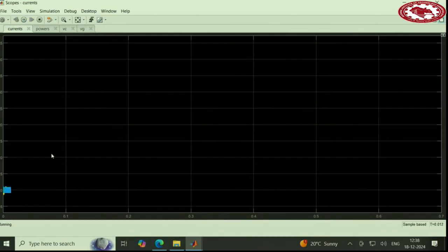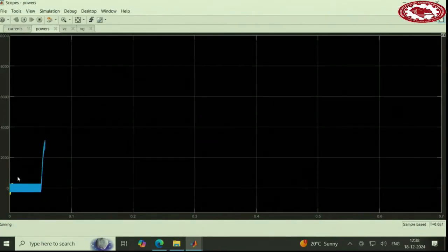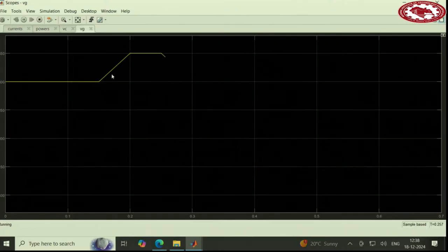So this shows the currents of the two converters starting from 0, and then the set point of power is 0, and then the set point goes to 3 kilowatt and then to 6 kilowatt. So 2 step changes, 3 kilowatt, 6 kilowatt. And then here is the disturbance on the grid happening. If you look at the grid voltage, it's going up.